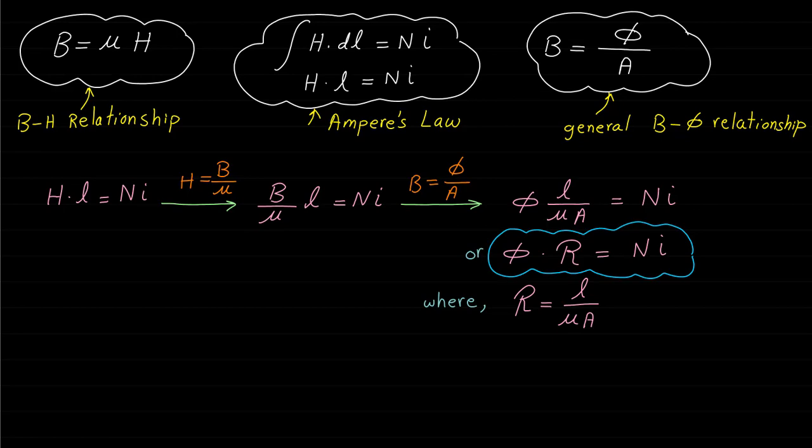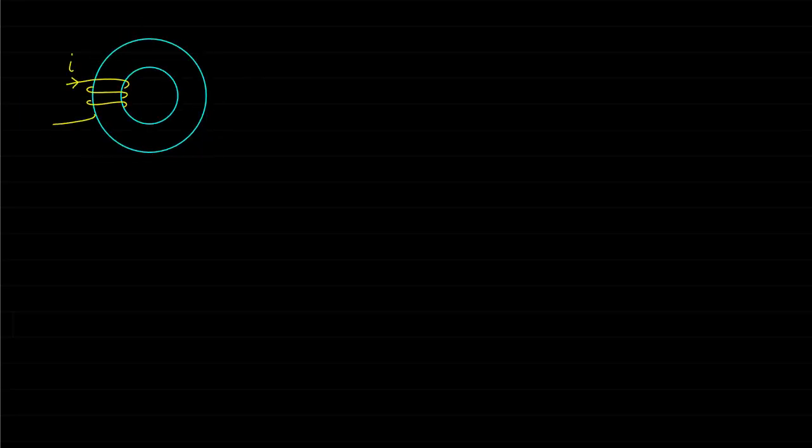In general, for any equivalent magnetic circuit, the coils and currents are converted to MMF, and any medium must be considered and converted into a magnetic reluctance R. The medium could be a magnetic material or non-magnetic material such as air. Now assume we have the following magnetic circuit.